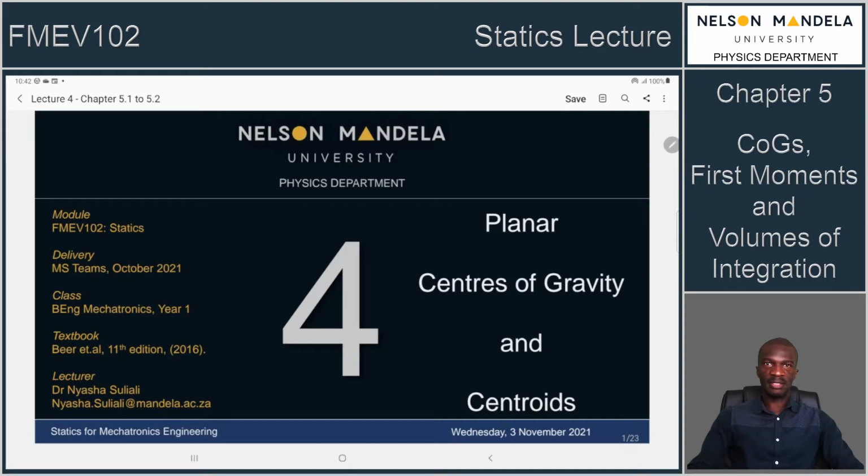Then after converting to some resultant force at a particular point and the moment resultant, we noticed that you can actually decouple that resultant force and its moment resultant into what we call a wrench. So a wrench would mean that you get a scalar product of that moment resultant onto the resultant axis. Then you would have another axis, so that if you move your wrench to another convenient point, you actually eliminate the lateral moment vector.